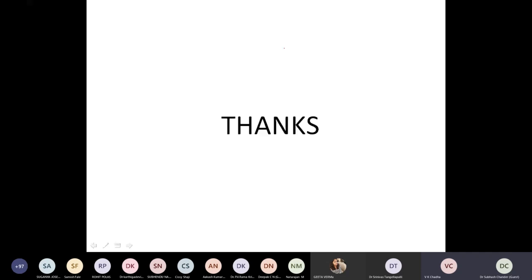Yes, sir. So in your applications, you are trying to give more surface area, more contact area, to the air surrounding it, so that heat transfer is enhanced, because it is a low temperature application. Low temperature we generally consider as less than 100 degrees Celsius. For less than 100 degrees Celsius, the predominant mode of heat transfer is convection.